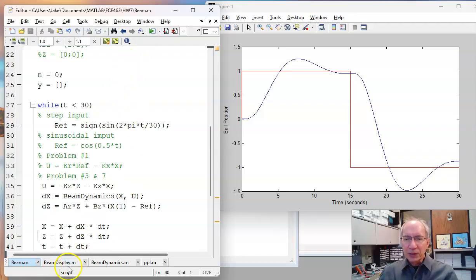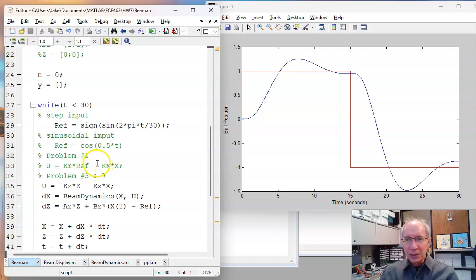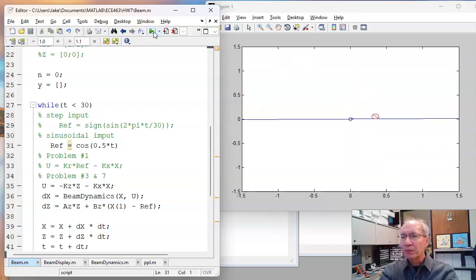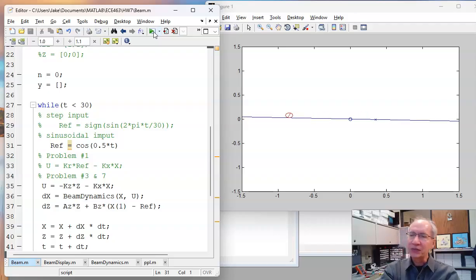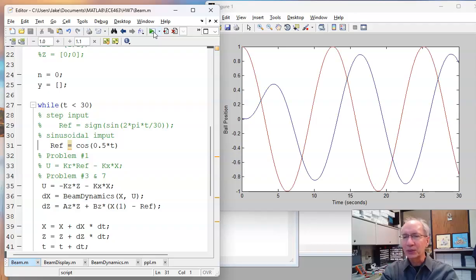Now a problem with the servo compensator is, let's go back to the nominal case. It works for a constant set point. It doesn't work for a sinusoidal set point. So suppose I did this. Can I track a sine wave? Well, it does track a constant, but it's not designed for sine waves. It cannot track a sine wave. So tell it to track a sine wave. It's trying to figure out what constant I need to hold the output at the set point. Well, the input that I need isn't a constant. So it's trying, missing. Doesn't work for sinusoidal inputs.